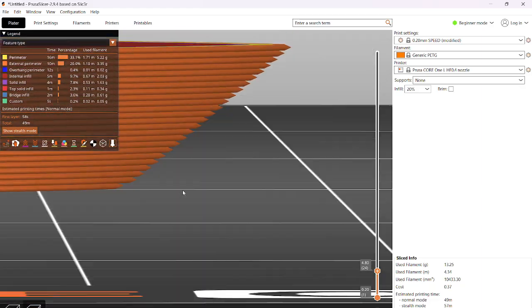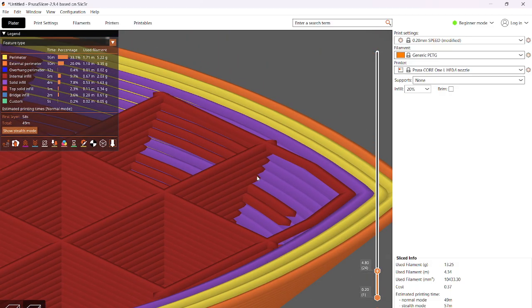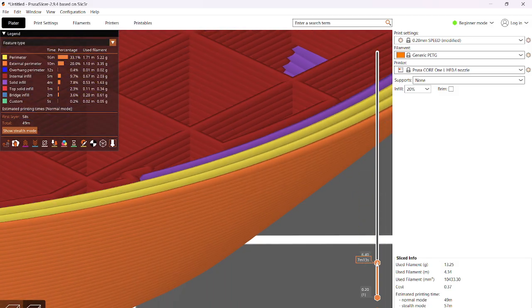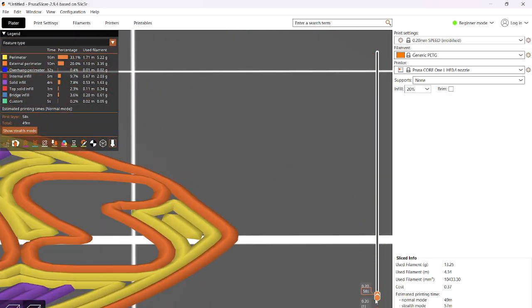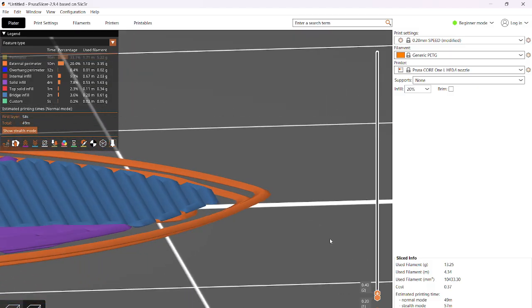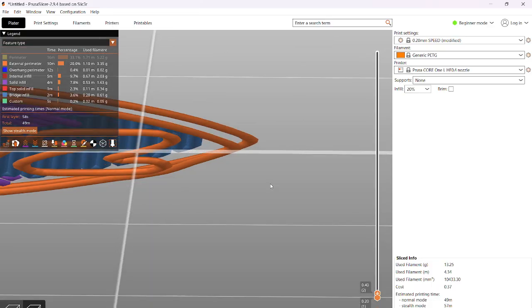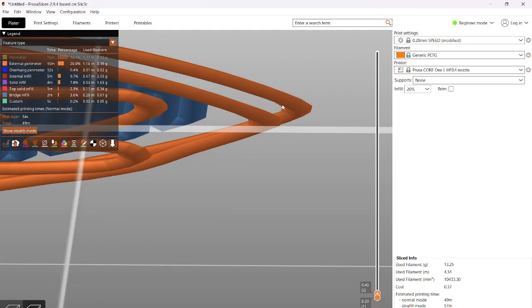So this overhang is somewhat aggressive. It's not super bad, but maybe it might be visible on the second layer. Can I hide? Yeah, okay. So you can see I hid the internal perimeters, and you can see these two external perimeters. There's a very small gap in between this, right? At this point, the material is almost overhanging by 100%. There's nothing supporting it underneath. And when you have that, you start to get drooping and stuff like that, and then you'll need to have supports, right?